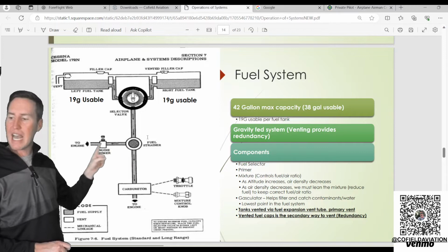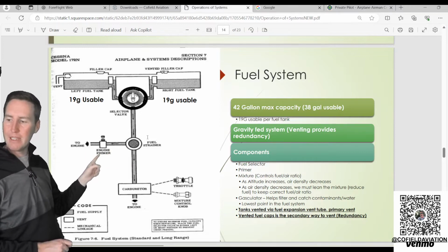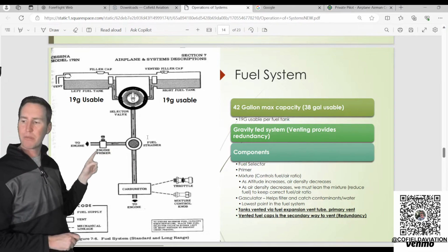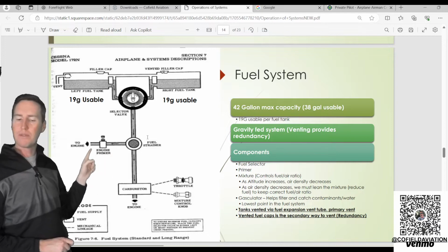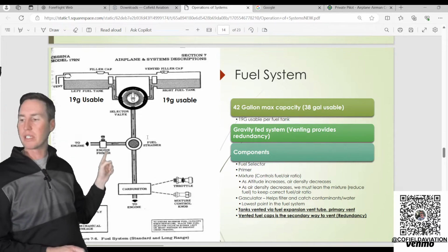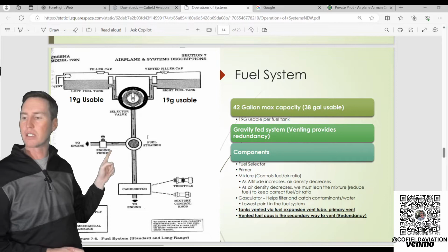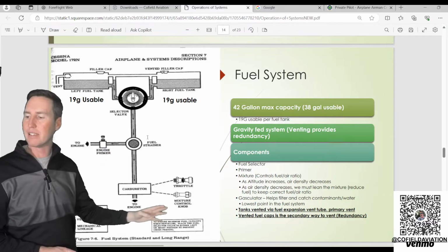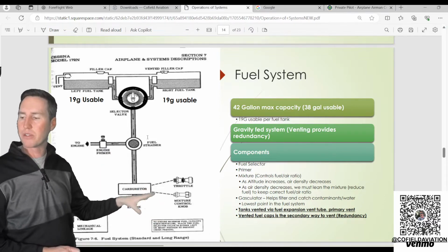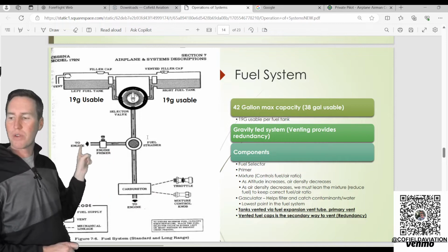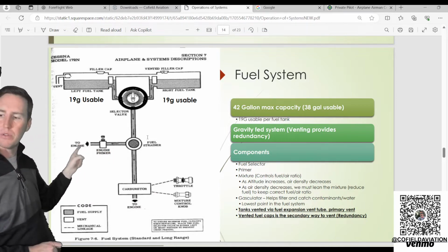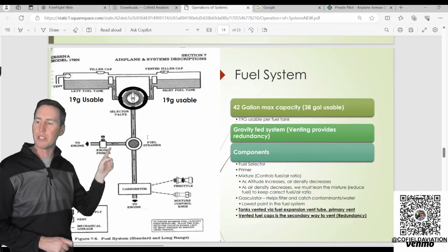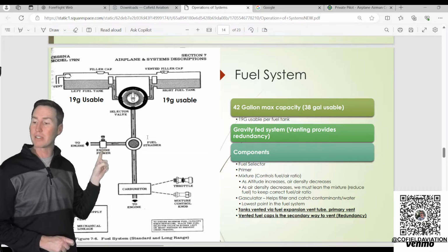Okay, what we can tap off of that is an engine primer. So we have an engine primer. It's only used for engine starts when it's really nice and cold. Otherwise, this is always locked in position, but it bypasses the carburetor mixture control and all of that and goes straight and dumps fuel directly into the cylinder only for engine start. You would not want to use this at all in flight because guess what?